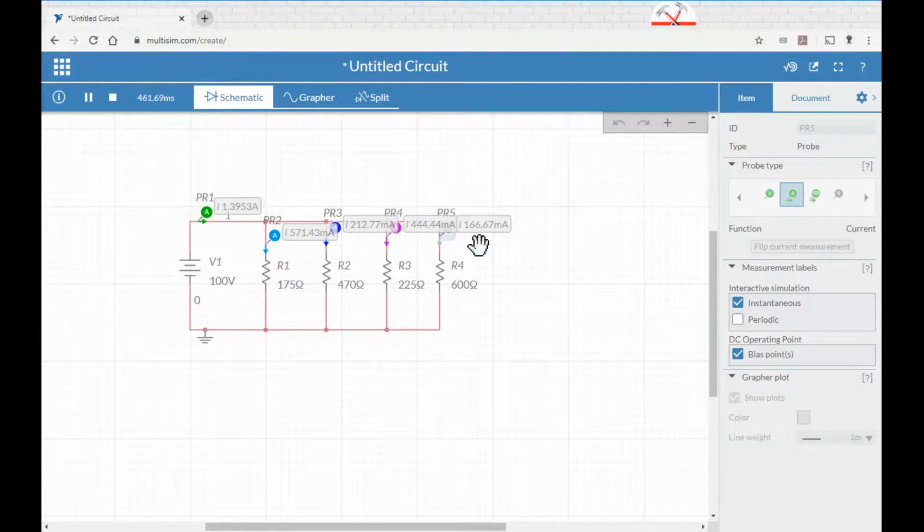Not a problem, okay? Because when I say milliamp here, we're talking about 500. So the milliamp place, in this case, is the least significant bit of a 3 significant figure value, okay? So I'm not worried about a milliamp here and there in this particular case. Okay? Any questions? So there you go. All that work that we did on the board, Multisim did at the drop of a hat.